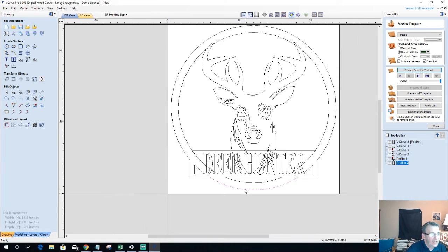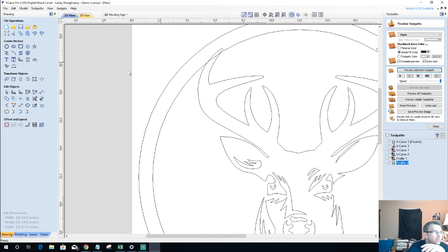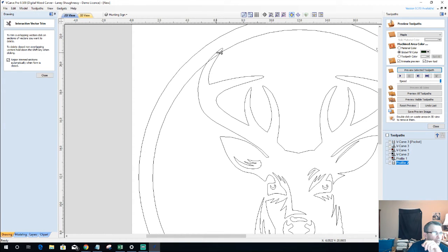Here I've got to decide, do I want this door hanger to have this full round down here, or do I just want to get rid of these, right? So it has this final shape of this, and I like this shape better than the other one. Now up here, same thing. There's no tool that's going to give me a better option than just interactively trimming, and all I'm doing is trimming two lines. This guy here.